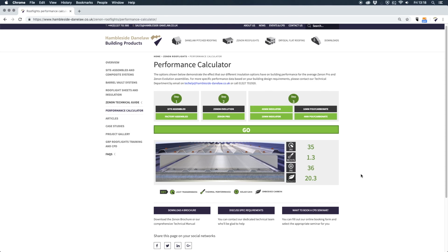There is something we can do to improve the light transmission, and that is to use our Insulator Honeycomb core. And if embodied carbon is an important consideration in your brief, then you'll like this. The light transmission is back up to 46%, and the overall embodied carbon figure has gone right down to 15.2 kilograms. With this final assembly, we end up with excellent non-fragility, good light transmission, moderate G value, improved thermal performance, and all for an embodied carbon investment of 15.2 kilograms. That's 25% lower than the baseline construction we started with.